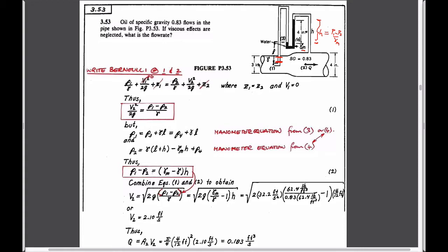If it is pointing upstream, you can also solve it, but you won't be able to use this particular form of the expression, because now you're not just measuring pressure at this point, but you're measuring a pressure that is due, not to the real ambient pressure here, but to the fact that you're stopping a velocity, and the velocity at this measurement point has to be 0. And so it's a little more tricky than that.